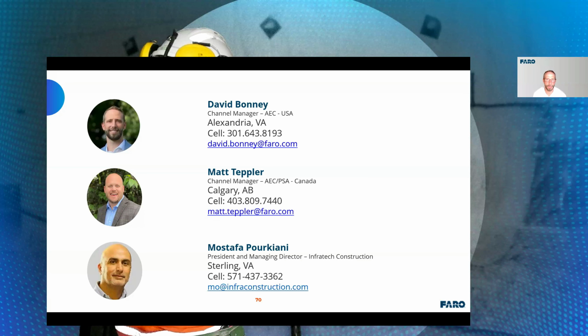Second question: how long would it take and what tools and scanning mission are recommended for a hospital with several wards and buildings in the same venue for BIM 3D data acquisition? Matt, you want to take that one? Yeah, we do have a data set that we can share if someone wants to see it, of a project we did in London, scanning the whole hospital in less than a day. From a mission perspective, it depends on the level of detail, as Dave's saying. If you were trying to model electrical conduit, then you're going to be using a terrestrial. If it's more where the wall spaces, windows, and openings are, as-built type situations, you can easily scan that in under a day, and we have.